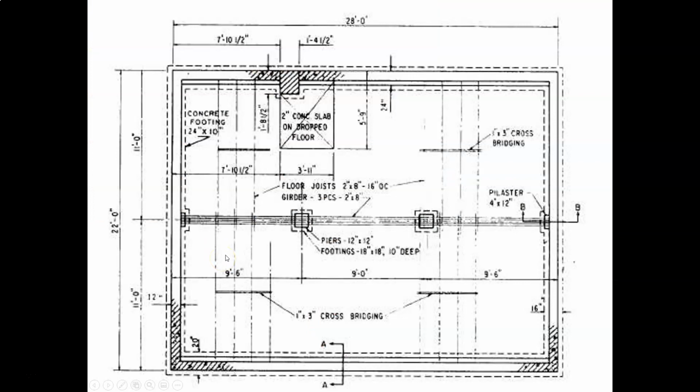Okay, so this is a plan. This is like an illustration or kind of an old-fashioned looking plan, but it has good information in it. That's why I included it. So here is the foundation wall right here. Let's just cruise around and let's see what we see first. So I see dimensions on the outside. I see here dimensions. So go back to where I was. That's the foundation wall, and the dashed lines below are the footings.